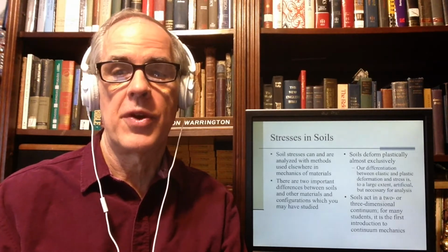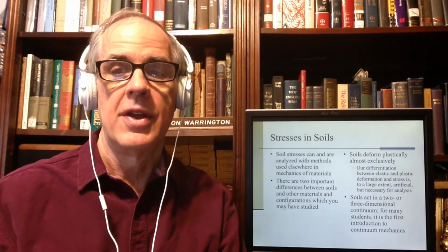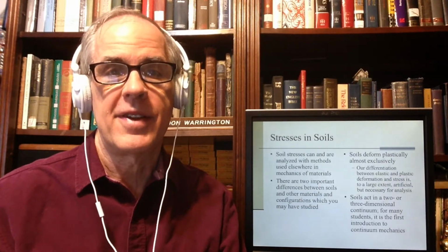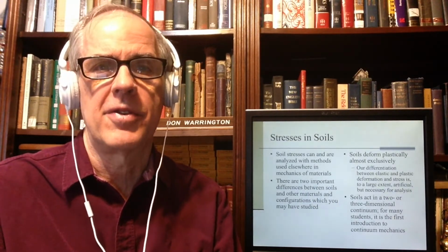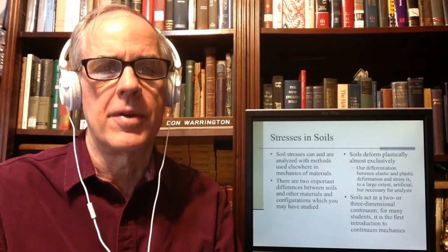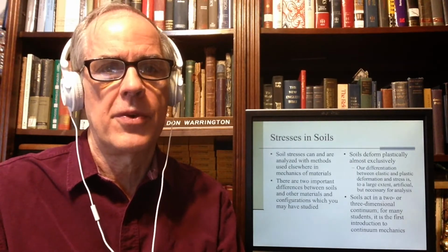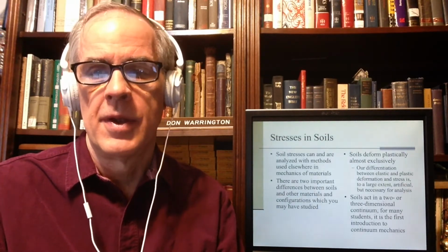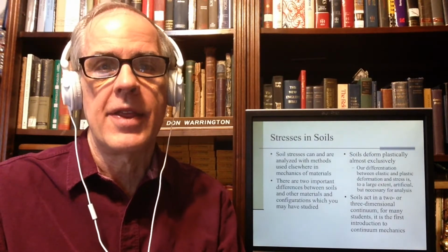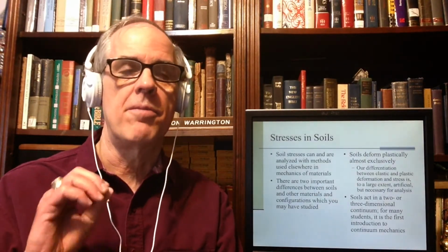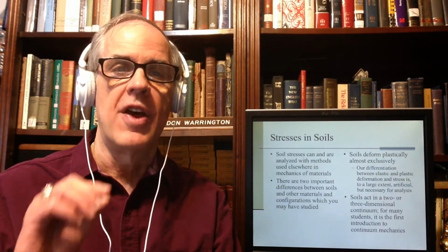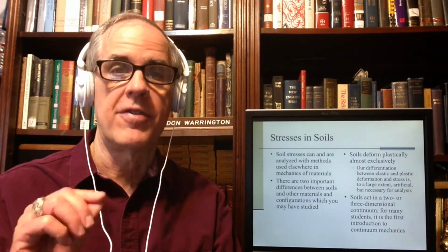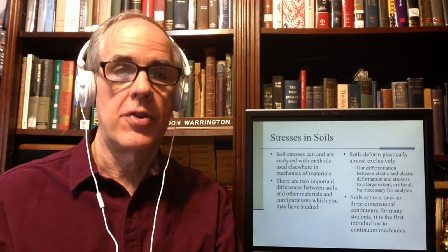There are two things. One I've just mentioned: soils deform plastically almost exclusively. There's very little such thing as a true elastic deformation of soil. Rocks are a little different, but with soils, not so much. That's one thing that throws students, because most early mechanics of materials education focuses on elasticity, and justifiably so. There are good reasons to do that.